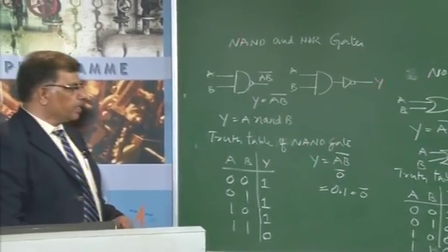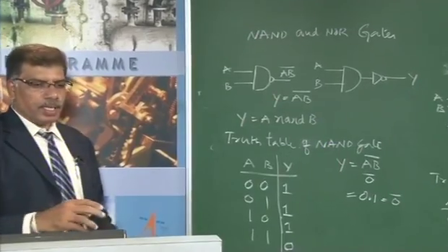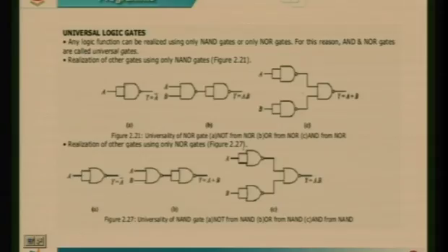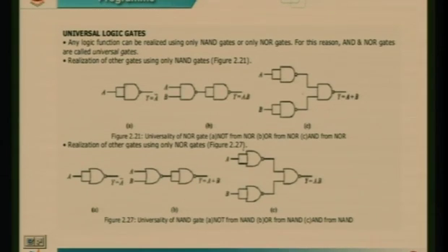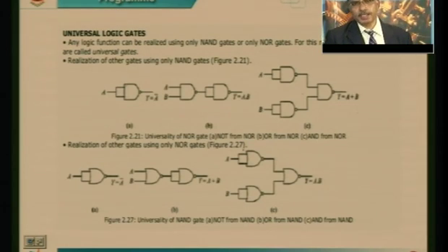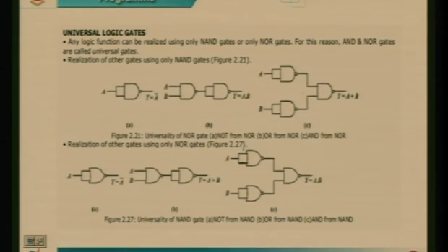These basic gates plus the universal gates will be utilized to build bigger logical circuits. As I said before, NAND and NOR gates are universal gates, meaning that by using these NAND and NOR gates we can build basic circuits. Instead of using an OR gate and an AND gate, we can utilize only the NAND gate to build any logical expression. So I will take up some of the basic circuits and try to realize them by using only the NAND gate. We will take an example and try to do that.